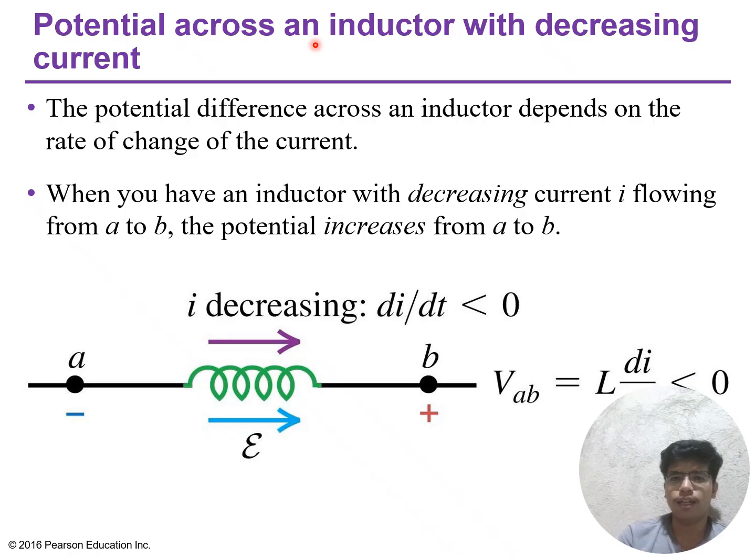So a fast decrease in a large inductor produces a large voltage spike. This is why opening a switch with inductive current can generate dangerous back EMF. When a switch opens, the inductor's back EMF can damage components or cause arcing. So protective devices like snubber circuits or flywheel diodes provide a path for current to decay smoothly. The inductor discharges its stored energy, U equals 1/2 L i squared, which is dissipated as heat. So the decay follows the same time constant, tau equals L over R, as the growth in current. In AC circuits, these produce sparks if no controlled path exists for the energy in the magnetic field.